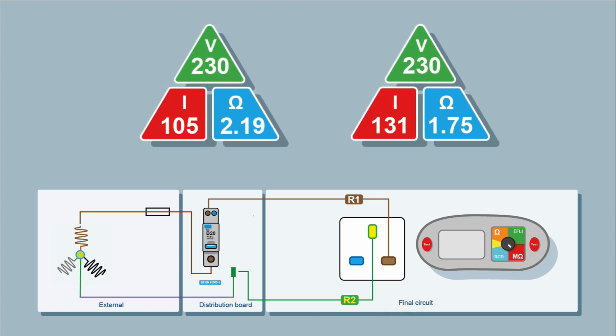If you do have a fault, the fault will follow that path. So you have a short between line and earth. The fault current will go down the CPC, through the main earthing terminal, back to the transformer in the street, back through the service fuse, into the protective device, and operate the protective device, switching off the circuit, removing any danger. That is your earth fault loop impedance path.